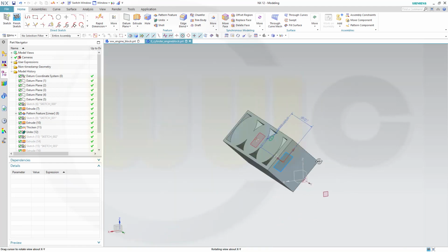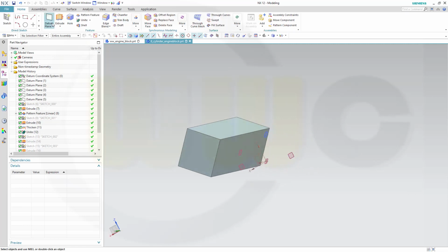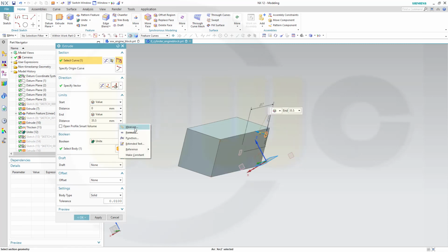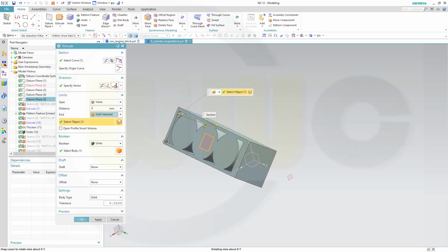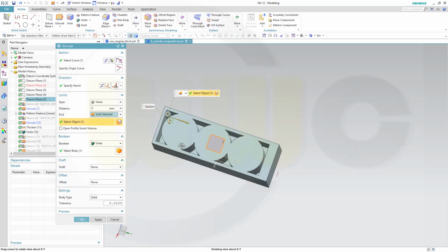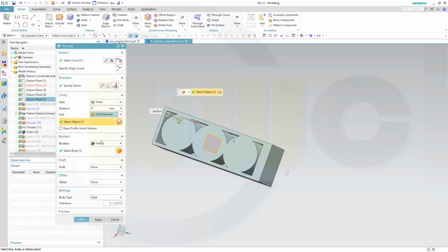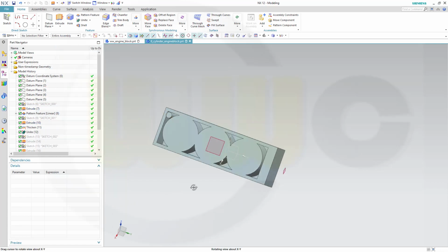Let's make an extrude. Finish that sketch. Let's make an extrude with that circle, and it should go up until selected, so to that plane. And of course I could unite, or I could wait and unite afterwards. I will unite afterwards, so let's go for none, and okay.